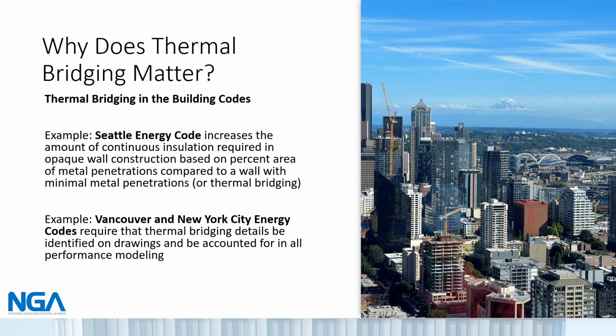Why is this important? Building envelope thermal performance is a critical consideration for reducing space heating loads and will be an increasingly important factor as codes strive for lower energy consumption in buildings. Thermal bridges allow uncontrolled heat flow to bypass the envelope insulating layer, introducing uncertainty of thermal performance, and thermal bridging enhances the risk of inefficient design in HVAC, building operations, inadequate condensation resistance at interfaces, and compromised occupant comfort.